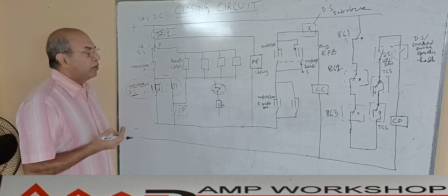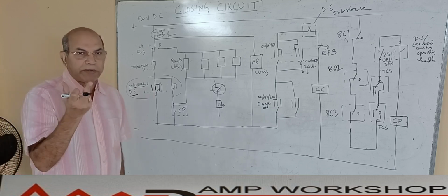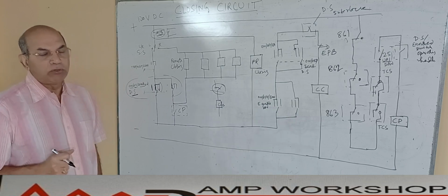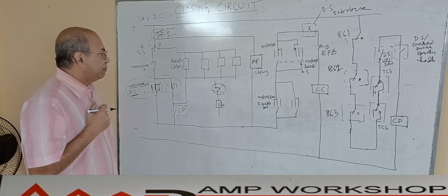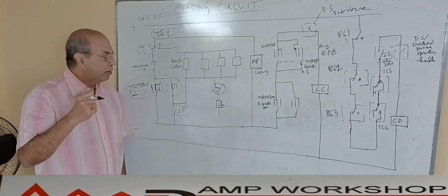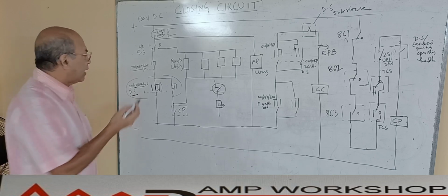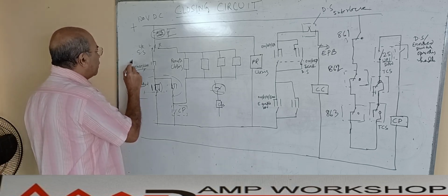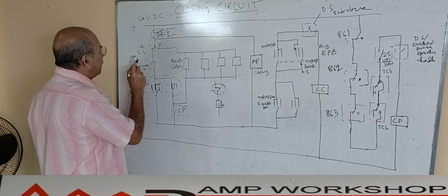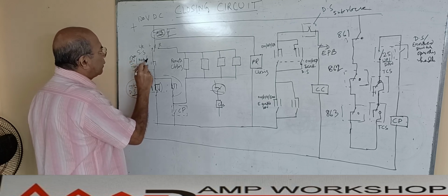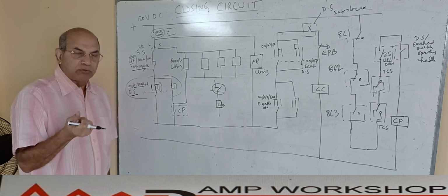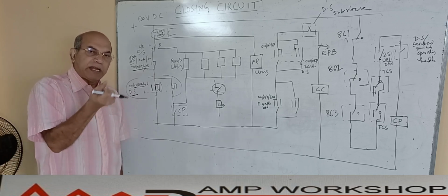Then from the local position I am going to close the breaker. On the switchgear local panel, there is a manual switch, we call it a breaker control switch, BCS. That breaker control switch has 3 positions: trip or open, neutral, and close position. Neutral means nothing will happen, and this is on position or close position. We call it a trip neutral close switch or breaker control switch. This switch can be used for closing purpose as well as breaker opening purpose.